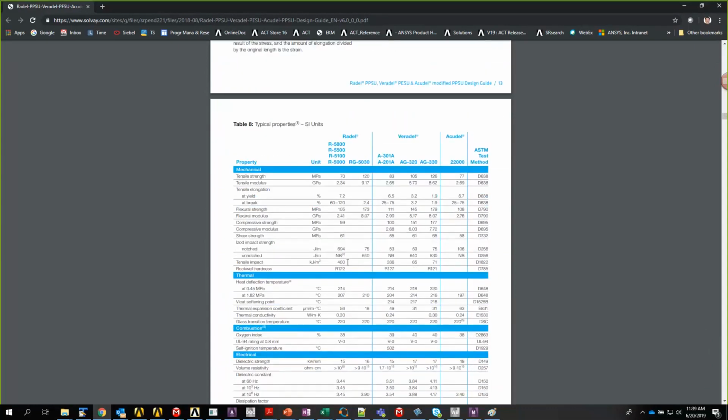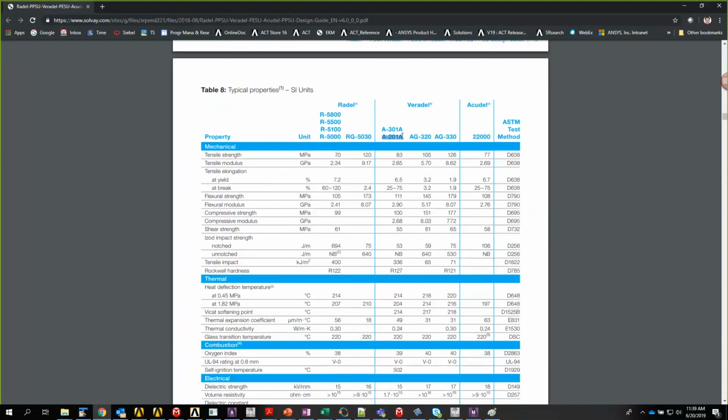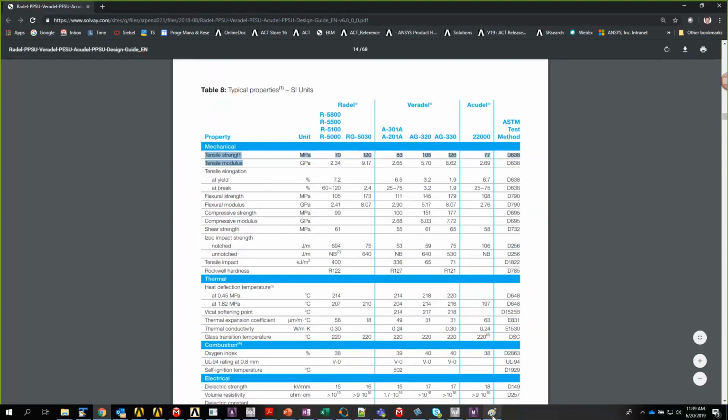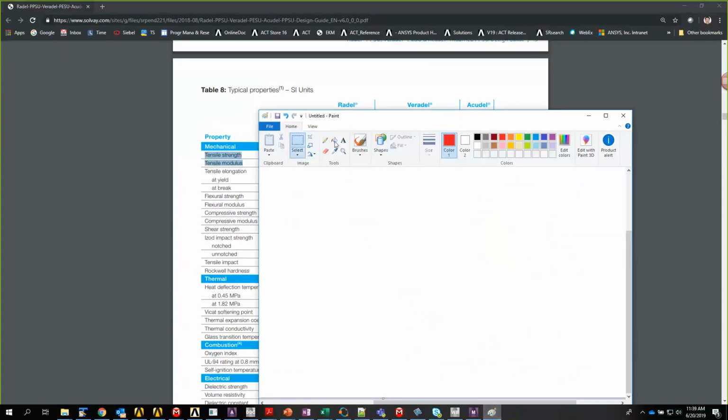Okay, so what we are looking at is, this is our product. Basically here, when we do the interference fit, the material is mostly undergoing compression rather than tension. So this particular material is assumed to have a different stress-strain curve in tension, and the stress-strain curve in compression looks different.